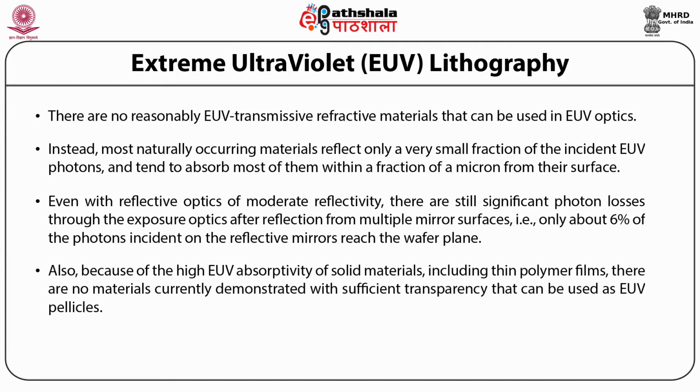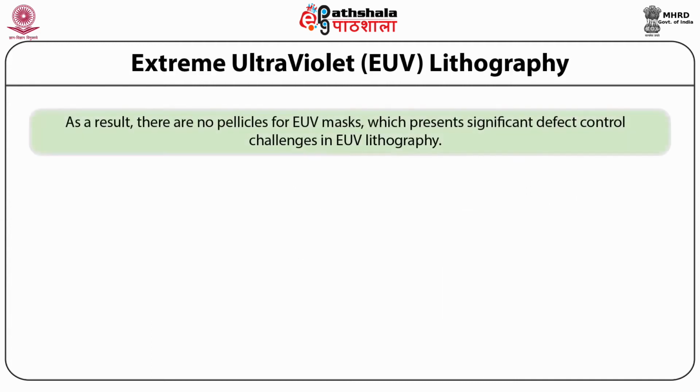Also, because of the high EUV absorptivity of solid materials, including thin polymer films, there are no materials currently demonstrated with sufficient transparency that can be used as EUV pellicles. As a result, there are no pellicles for these masks, which represents significant defect control challenges in lithography.